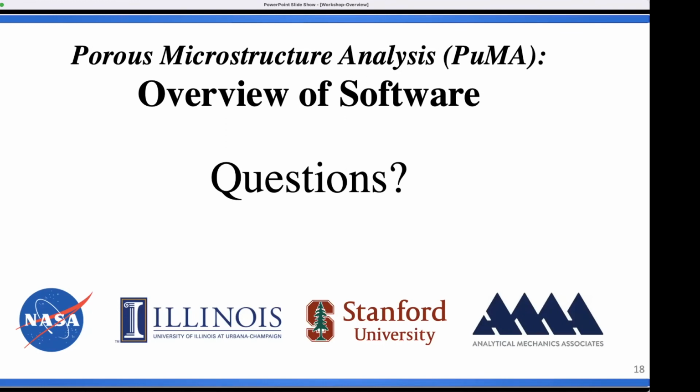Real quick, sorry. I think if I'm understanding that correctly, they're talking about moving from a global model to the microscale model. So I think they're talking about macroscale and microscale here. Typically the way that interaction would work, it's not a direct coupling. You use the microscale to calculate, say, your effective elasticity. And then in your macroscale model in Abaqus or whatever else, you would input that effective elasticity as the material property, which would be just an input for the volume averaged model that you're using.